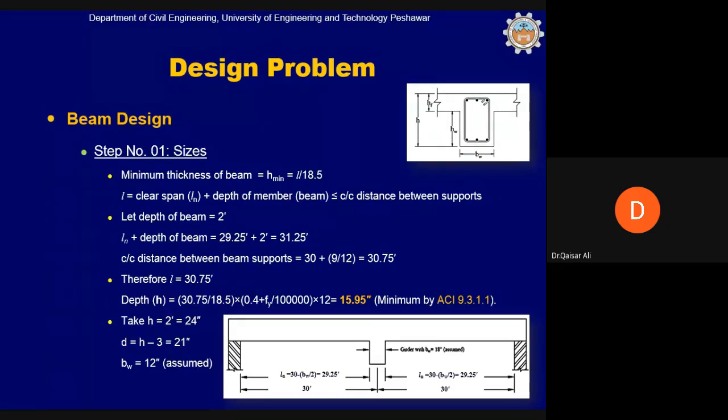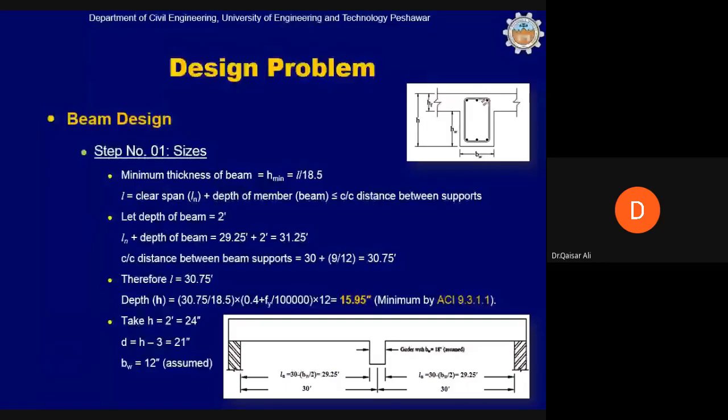Okay, this is a beam which is simply supported at the ends and continuous at the intermediate support. So the bending moment diagram will be with a positive bending moment and negative bending moment, then a positive and zero. Zero, positive, negative, then again positive.